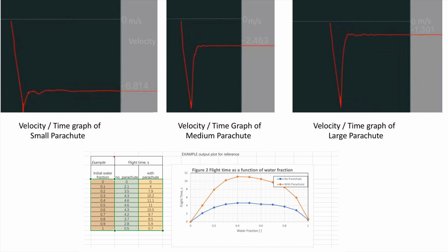The parachute will increase air resistance during the fall, therefore reducing the terminal velocity. This increases the time in the air, but making it too large will mean it takes too long to deploy, so the rocket has lost too much altitude before deployment.